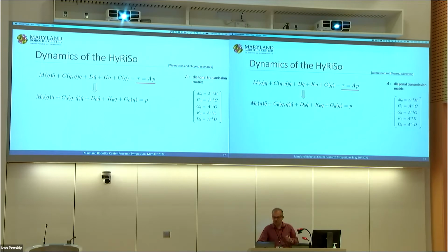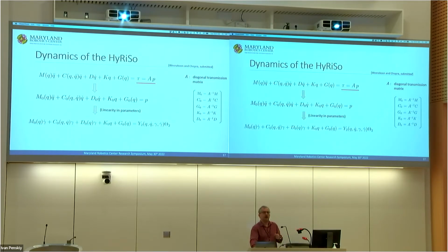So we showed here that it's actually possible to adopt a similar framework, and it pans out fine, even when I don't know the actuator mapping. We have to reparameterize in a particular way, and we can then apply the classical methodology. So you see on the right there, we have a vector theta2, which is a vector of all the unknown parameters, maybe the mass, the stiffness. Well, it takes care also of the inverse of the actuator mapping in some way and other parameters.